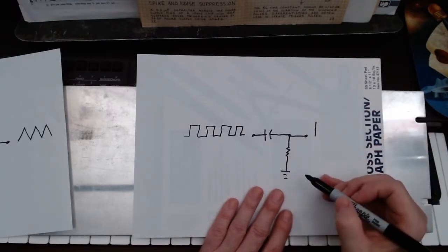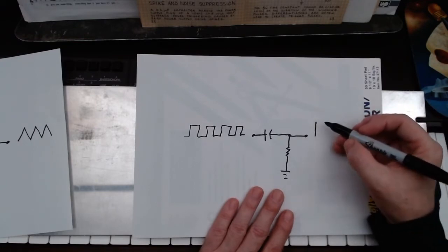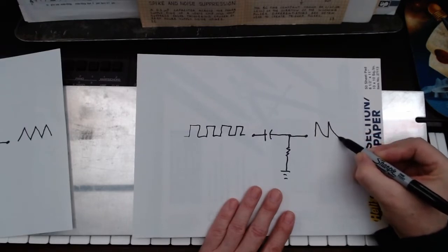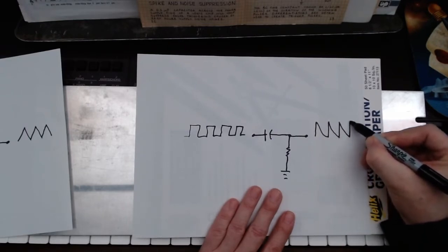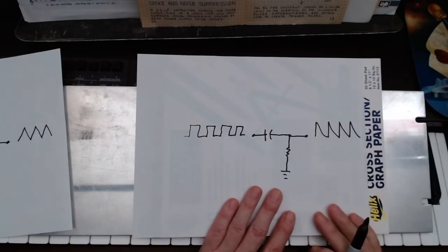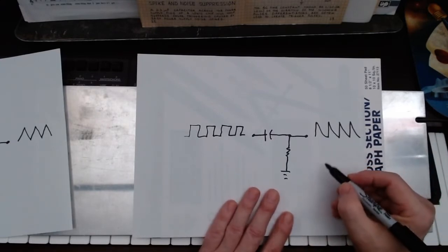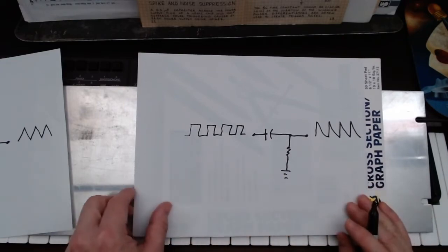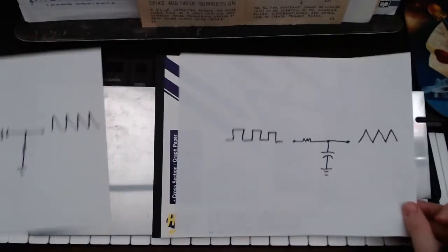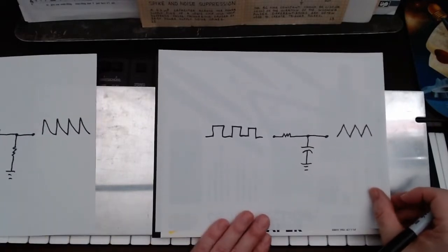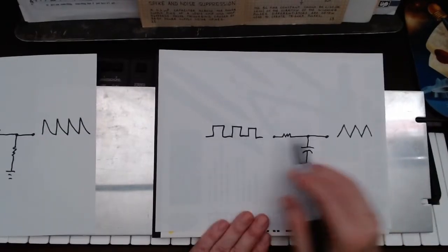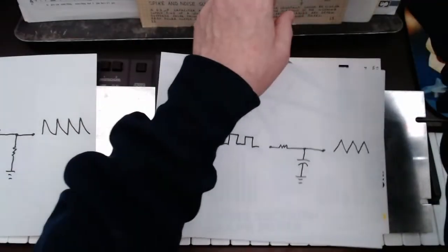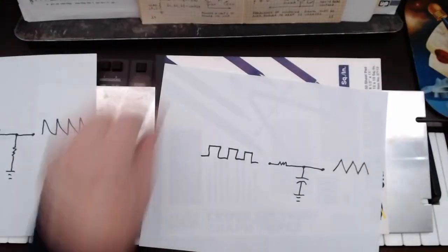The drain to ground is affecting that discharge by slowing it down, and now we get a sawtooth wave. And a sawtooth wave is very useful for certain organ tones like strings or smaller diapasons like Gem's horns, that kind of thing. Now, we showed how with an integrator circuit we can convert a square wave into a triangle wave, but I also explained that a triangle wave is not the most useful thing.